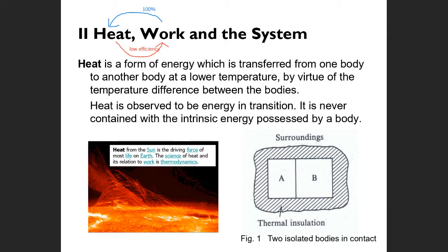For engineering thermodynamics, later we also understand the properties of the working fluid. When the working fluid undergoes changes of properties, usually for those processes there's a change of energy. There is energy transformation. And here again about heat. In fact, heat is the form of energy which is transferred from one body to another at a lower temperature. So when there is temperature difference, there is heat transfer. Heat transfer is always from the high temperature body to a low temperature body, in the case of conduction if there's direct contact, or convection if there is a solid and a fluid surface, and also radiation.